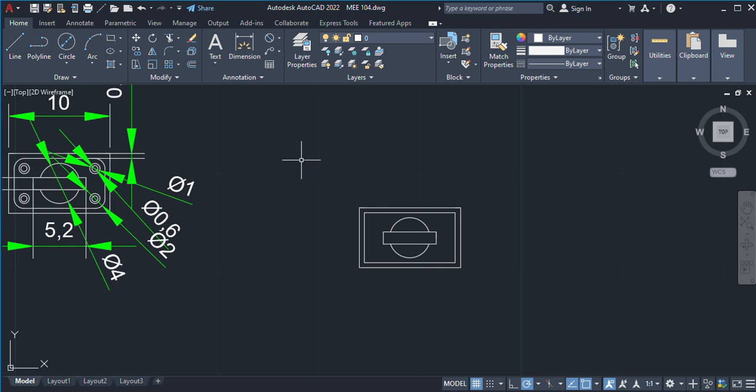We have something called fillet. So these are fillets here. You see now, I'm going to do this one. I'll do this one for the 3 sides. I'll not do the one that I taught us for just one side. So these are fillets. If you want to fillet, don't fillet the edges of here. So just press like this. You now press your R, that's radius, R, enter. So radius what? 1, enter.